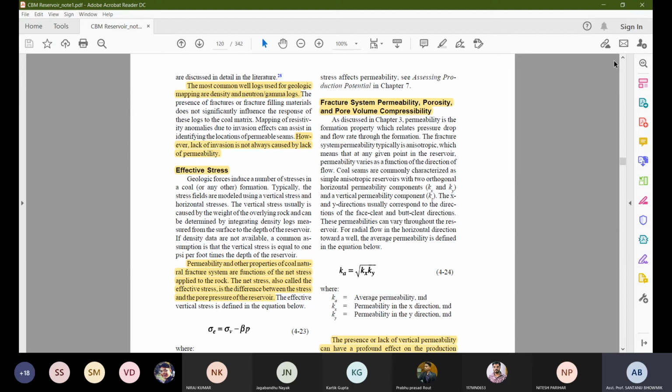Just like the concept of the Mohr circle, you have seen that whatever fracture surface will be created is obviously going to be dominated by the normal vertical load and the confining radial load. And that's why in triaxial compression you are going to get the angle beta of the fractures. In the new plane, you calculate angle beta as beta equals 45 plus phi by 2, where phi is the angle of internal friction. If you can remember the Mohr-Coulomb failure criterion, I am relating that for your better understanding. So for any average permeability, you have to consider this.